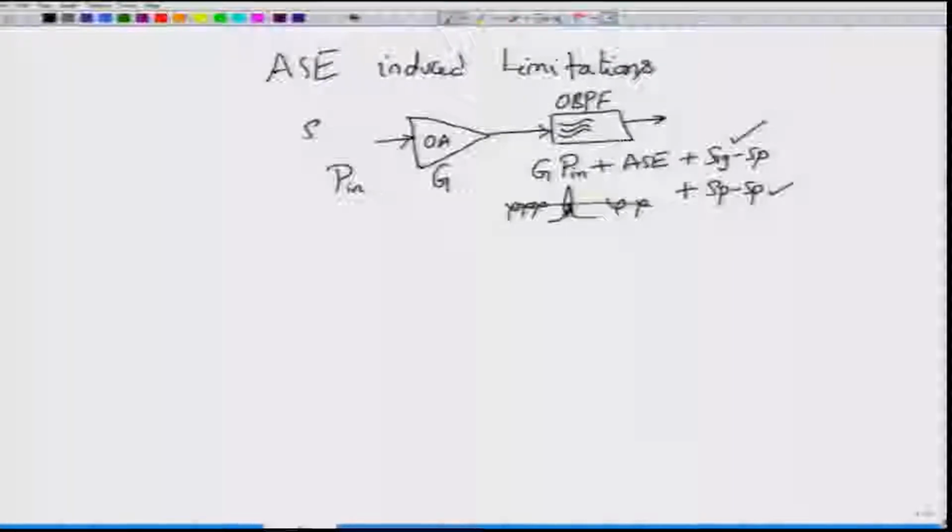The effect of the amplifier is to reduce, or rather worsen, the signal to noise ratio at the output, but this is not bad because without the amplifier you would not even be able to detect any signal. So, although the signal to noise ratio at the output seems to be degrading, this is offset by the gain, as the signal actually increases. This characterization of an optical amplifier, or any amplifier for that matter, is given by the noise figure of the amplifier, and for the erbium doped fiber amplifier under reasonably best conditions we saw that the noise figure will be roughly 3 dB.